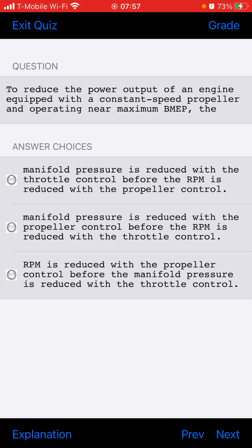What type of connecting rod are commonly found in radial engines? Well, we have the master rod and the articulated rod assemblies. What are the different types of piston rings? Well, we have compression, oil control, and oil scraper.